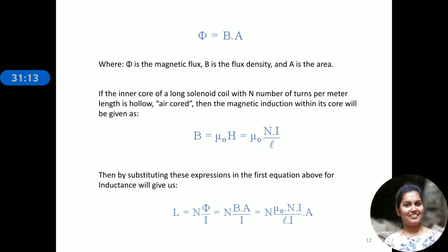For a self-inductance coil, or to be more precise, the coefficient of self-inductance depends on the characteristics of its construction, like N, L, mu, B, and these are all the factors, for example size, length, number of turns, etc. It is therefore possible to have inductors with very high coefficients of self-inductance by using cores of high permeability and a large number of coil turns.